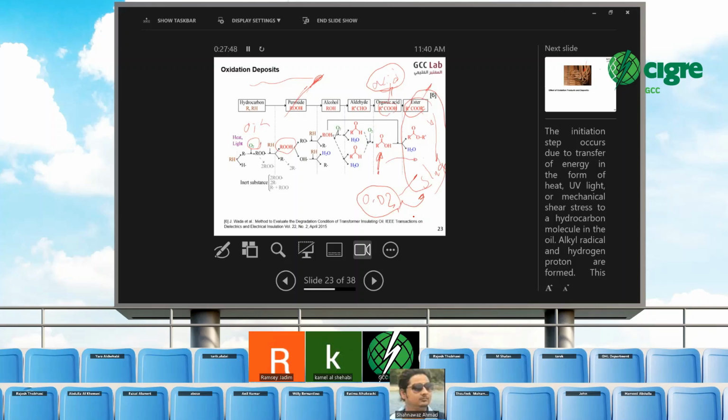Therefore, until now, ester is not the main test. The main one is acids. But if you have high acid, it is good to tell you that now you should do oil regeneration. Why do we tell you to do oil regeneration now? Because until now, you have no deposit.